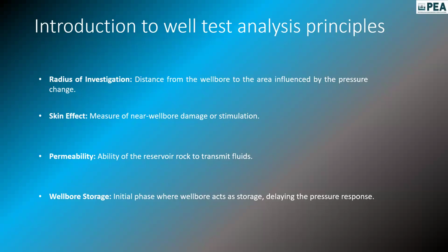Then you open the perforations. Ripples of pressure disturbance are generated near the openings and progress into the reservoir. Actually, it will not go totally into the reservoir, but towards the drainage boundary, because every well has a limited confined area that it can influence.